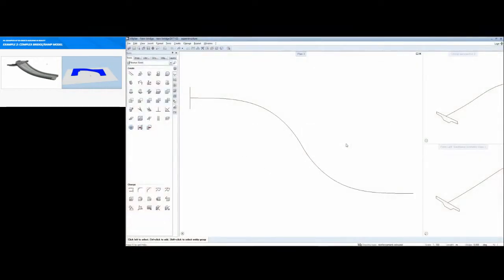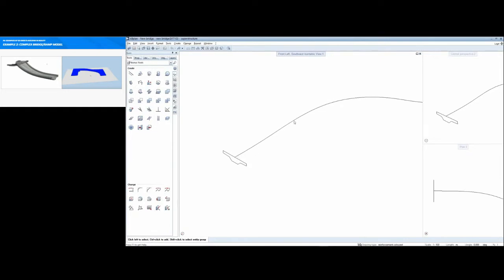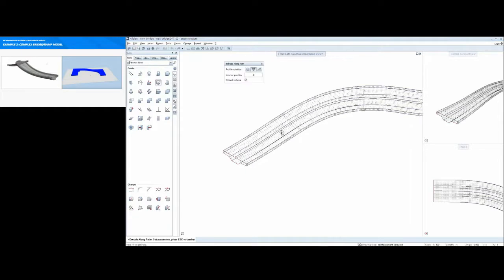In Allplan, the Extrude Along a Path tool is responsible for extruding a profile as prepared here along a curve to create an enclosed volume. The curve here describes the line of the bridge in terms of the ground plan and height. The Extrude Along a Path tool is used here to extrude the profile along a path. This creates a volume.